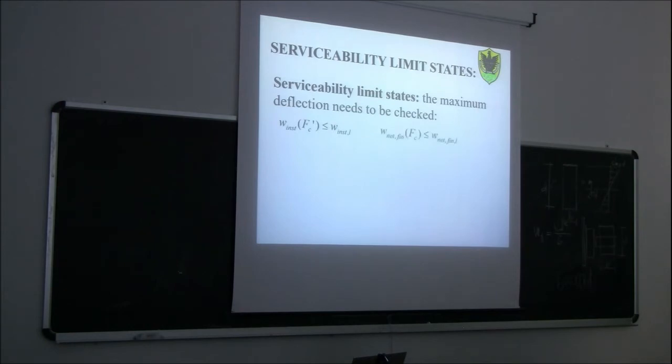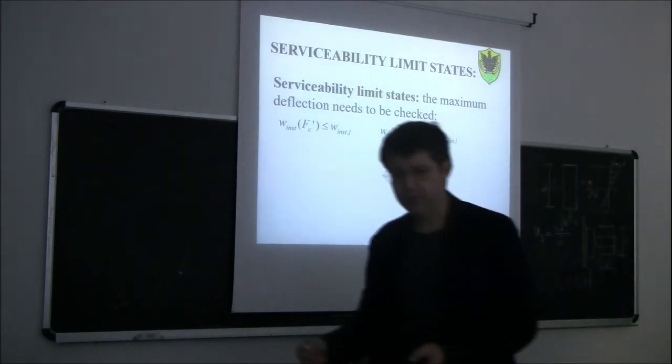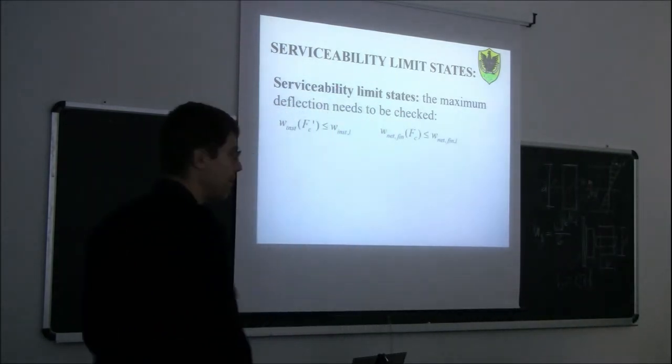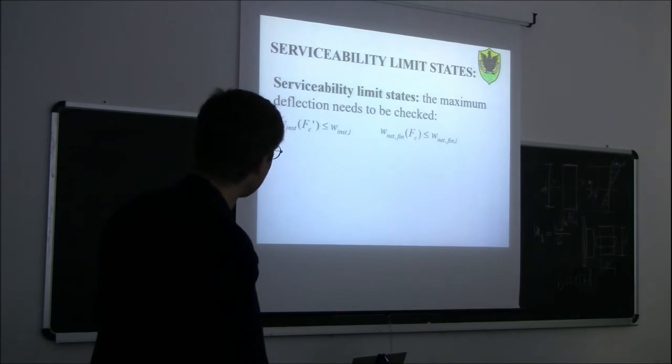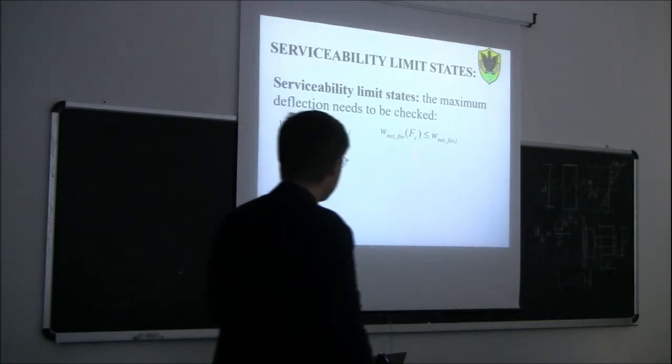So we have 2 checks, if you remember what we saw last time. If you design according to the national regulation, we have to calculate the instantaneous deflection under the variable part of the frequent serviceability limit state, and the final net deflection under the frequent load combination.